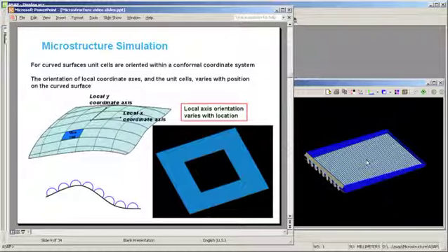This is accomplished by using a unit cell model, in which users construct a single cell within the repeated pattern of the microstructure. ASAP uses this single cell to simulate the effects of microstructure on incident rays. These effects include refraction, reflection, absorption, Fresnel or ghost reflections, and scatter.